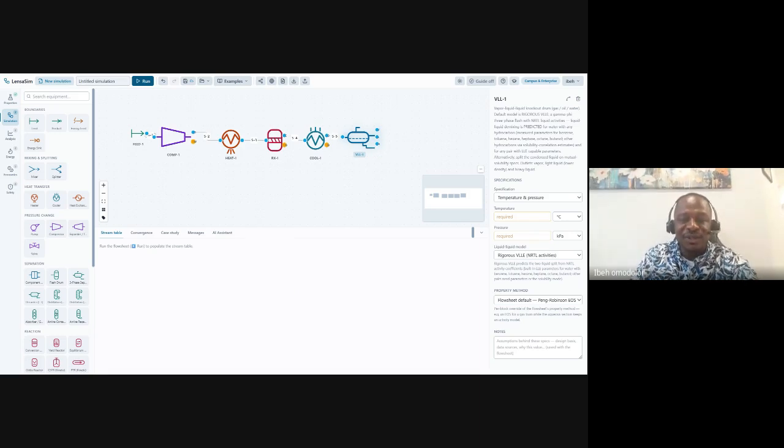If you are following me so far, just drop something in the emoji and we'll know that you are with us. Amazing. Awesome. The temperature we're putting now, since we have cooled it, is going to be 40 degrees centigrade, and the operating pressure will be 90 bar. So put your temperature here as 40 degrees centigrade, and then put your pressure here in bar. Consistency is very important, right? Don't put one in bar and another in kilopascal, except you are sure that you've converted them correctly. These are some of the mistakes I've also made when I'm not consistent enough.